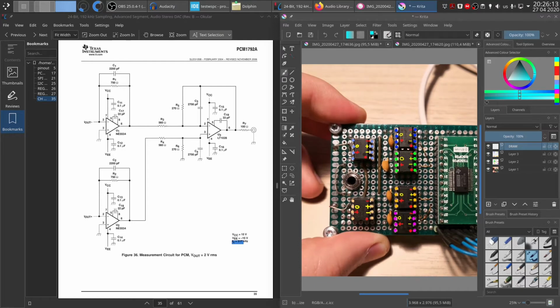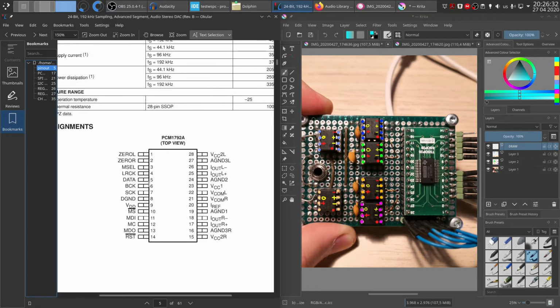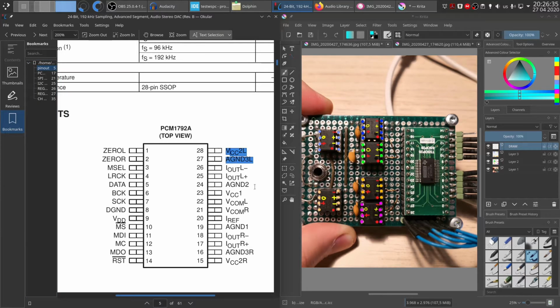So this is the digital part over here. Okay, so this is the digital part of the IC, and this is the analog part of the IC. Most of these analog pins, if we go to the pinout over here, are supply and ground, and common and supply, EREF again. So only these two pins and these two pins are the signal pins. So these are differential current outputs. These are the ones that we actually go any further with.